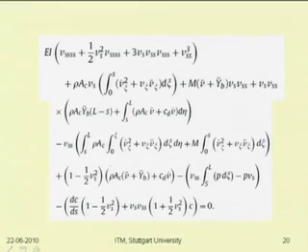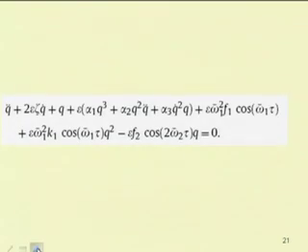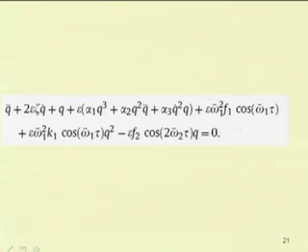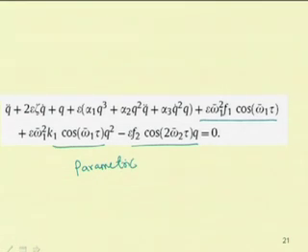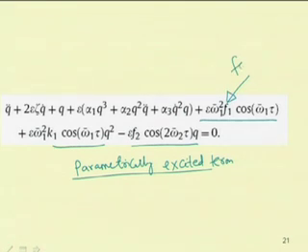What we have seen in the previous case, in that equation we have to add that of the base excitation, and in temporal form you can write this equation here. Similarly, one can apply a magnetic field and go on adding different terms in the equation. In this case, you can observe that this is a force term, that is epsilon omega 1 square f1 cos omega t tau, and these two terms. So, these two terms are parametrically excited terms and this one is a force excited term.